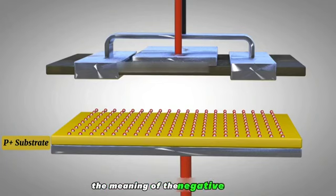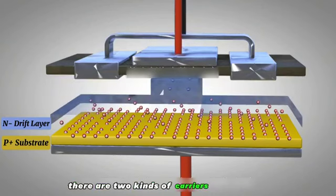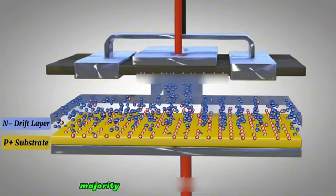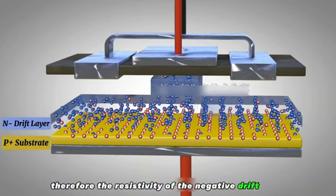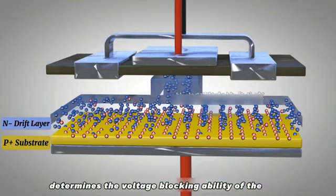The meaning of the N- drift layer is that, in the conducting state, there are 2 kinds of carriers in this layer: hole carriers and free electrons. The majority of carriers are free electrons. The drift layer is thick with low doping concentration. Therefore, the resistivity of the N- drift layer is extremely high. The thickness of the drift region determines the voltage blocking ability of the IGBT.